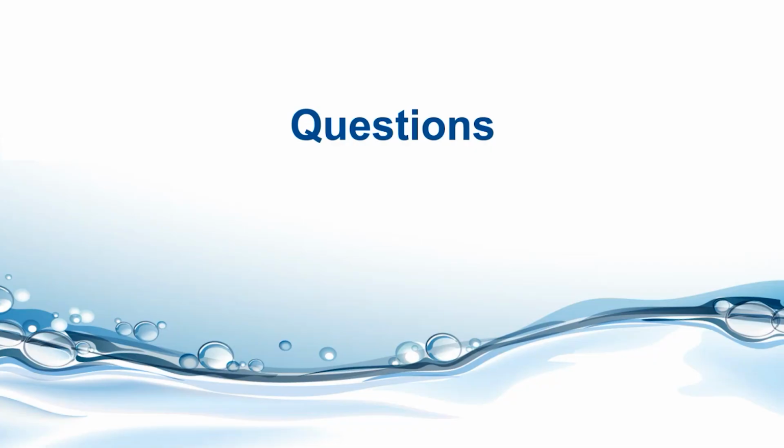Looks like a couple more have come in just very quickly. This one asks, you discussed the effect of excess ammonia on chloramination. Can you discuss the lack of enough ammonia? Well, sure. And if we look back at the curve that was shown, too much ammonia versus our chlorine means that we have that excess ammonia that can lead to nitrification.